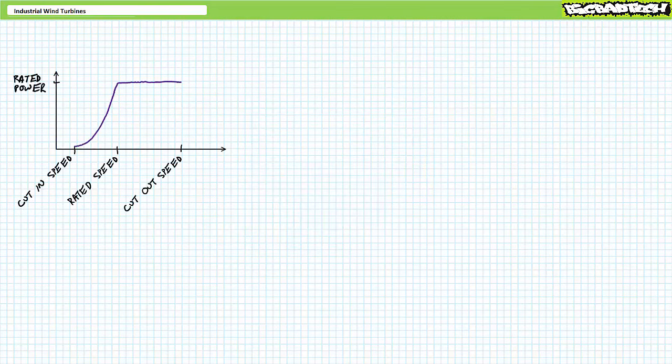As we learned in the wind and water power lecture, a wind turbine power curve looks something like this. From the cut-in speed, when the turbine is first capable of exporting usable power, to the rated speed, that speed at which the turbine reaches its rated output, the usable power output increases substantially given the cubic velocity term.